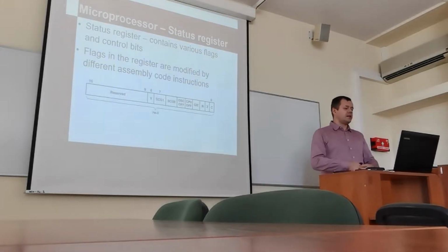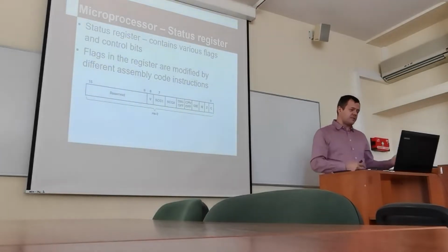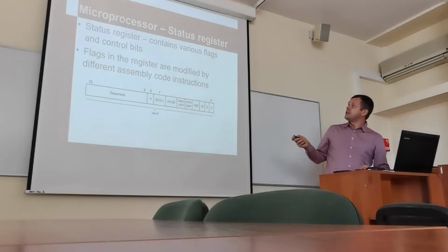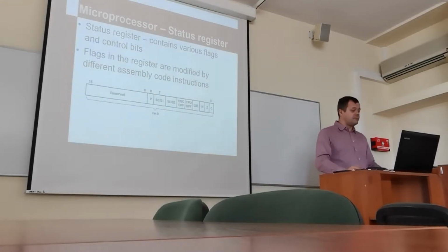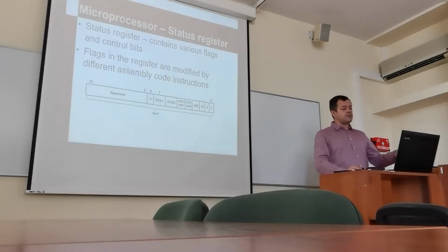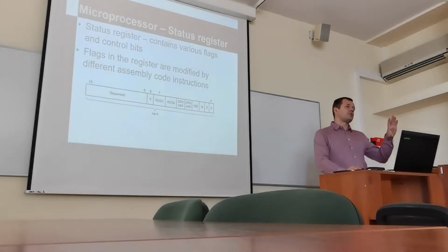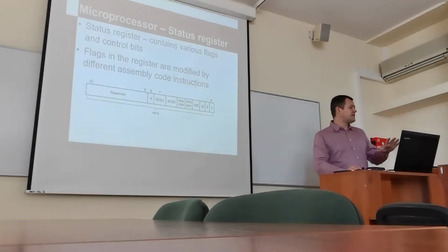Auxiliary registers, auxiliary elements to the microprocessor, because we mentioned two major ones, so the arithmetic logic unit and the instruction decoder, but there are also auxiliary elements. One of the auxiliary elements is the status register, always present in microcontrollers and microprocessors, of various kinds. This is the element where the major functionality of the status register is to be a temporary storage of status data of the arithmetic logic unit. Because